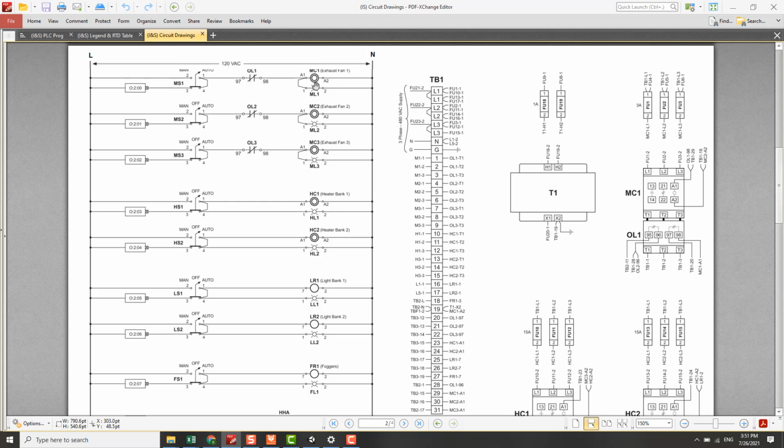Maybe one of the devices here: the PLC output switch, module 2 channel 0, the motor selector switch, the overload auxiliary switch, the normally closed auxiliary switch, or the wiring here has an internal open circuit, or there is a loose termination.